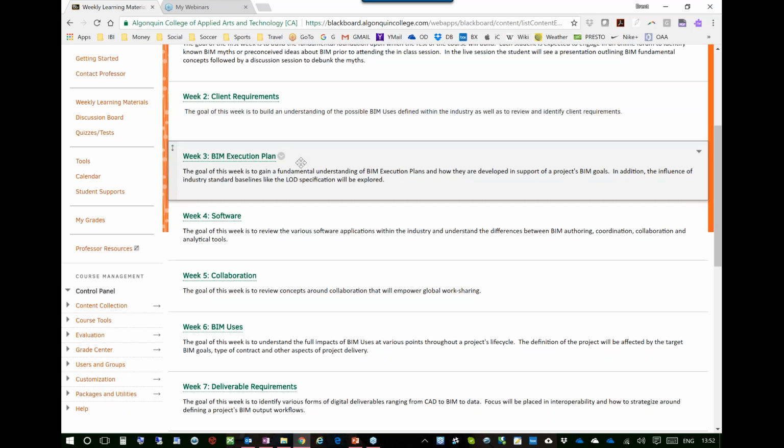You document the BIM uses, which we're going to expand upon next week in week 11. And we're going to document software, any hardware, any workflows, use workflows, which we'll talk about next week. LOD matrix, who's modeling what and when. And that's the most critical thing coupled into the legal and the project delivery. Who's modeling what and when. And everybody seems to forget the and when portion.